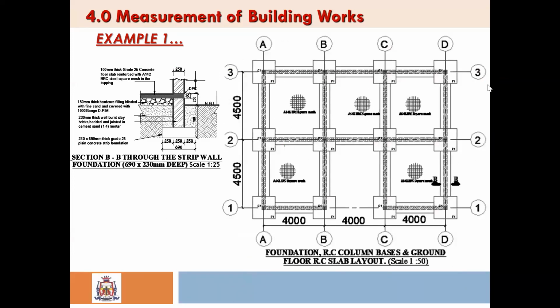Now you remember we had this making 4, and the 4 was setting center to center, okay? Now if it is center to center, that 4 meters, and you subtract the extremes of the walls, which are 230, you'll definitely get 3.77 as the internal dimension.